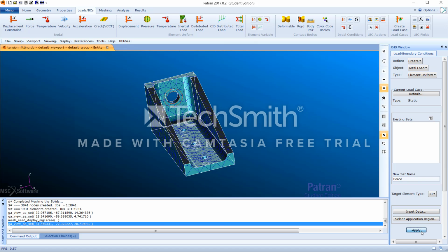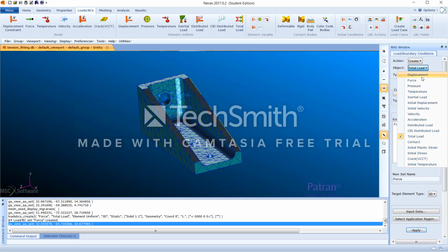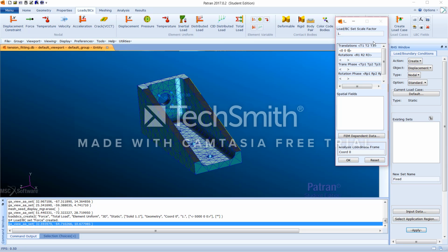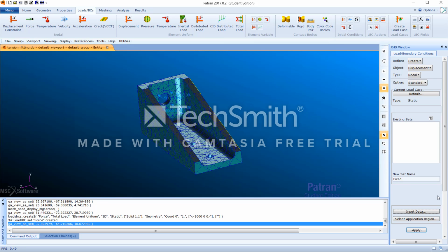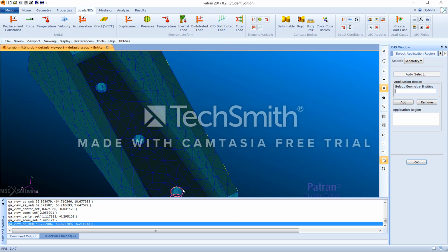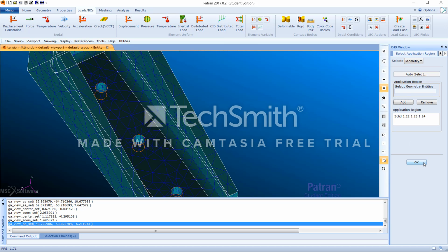To create the constraints at the base hole, set action as create, object as displacement, and type as nodal. Enter fixed as new set name, click input data, enter 000 for translation, and click OK. Select application region and click on the select geometry entities. Select the surface or face icon and select all the three cylinders faces of the three holes at the base and click add, OK, and apply it.